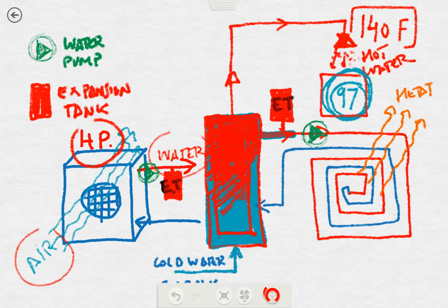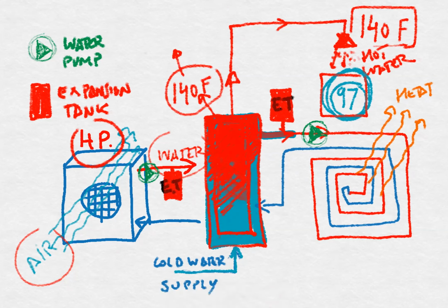Okay, so if our body is at 97, someone said before 110, yeah, kind of. But 110 is the temperature of the mix between cold and hot water. But the official temperature that we have to provide, here at the top of the tank, has to be 140. Why? Because there is some bacteria that we have to kill. And this bacteria is the Legionella.